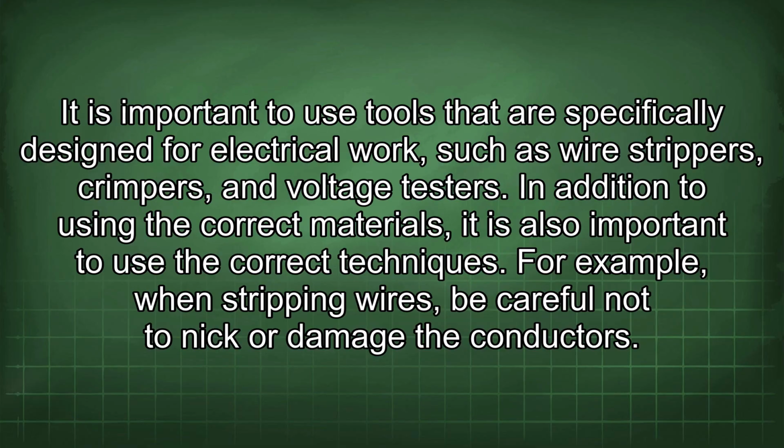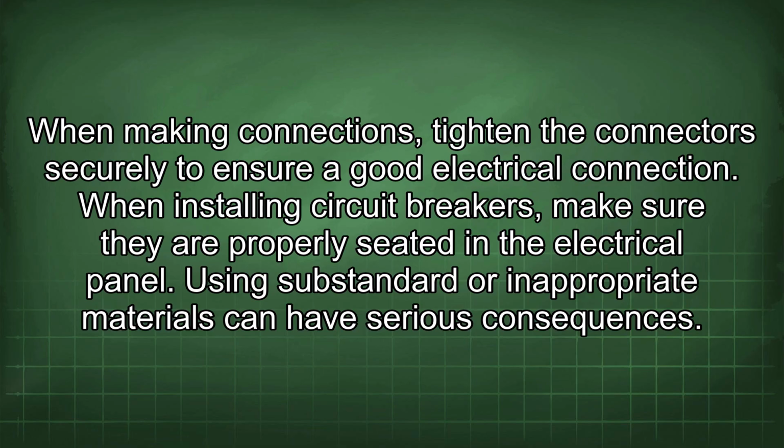For example, when stripping wires, be careful not to nick or damage the conductors. When making connections, tighten the connectors securely to ensure a good electrical connection. When installing circuit breakers, make sure they are properly seated in the electrical panel.